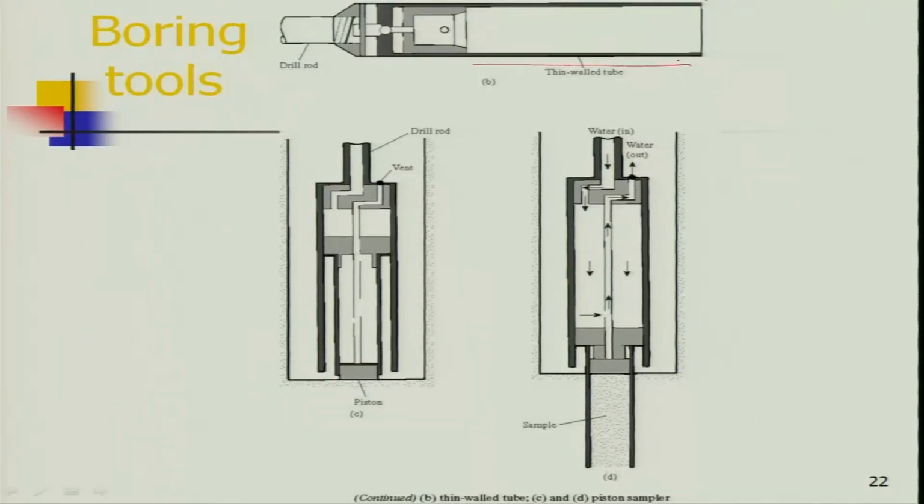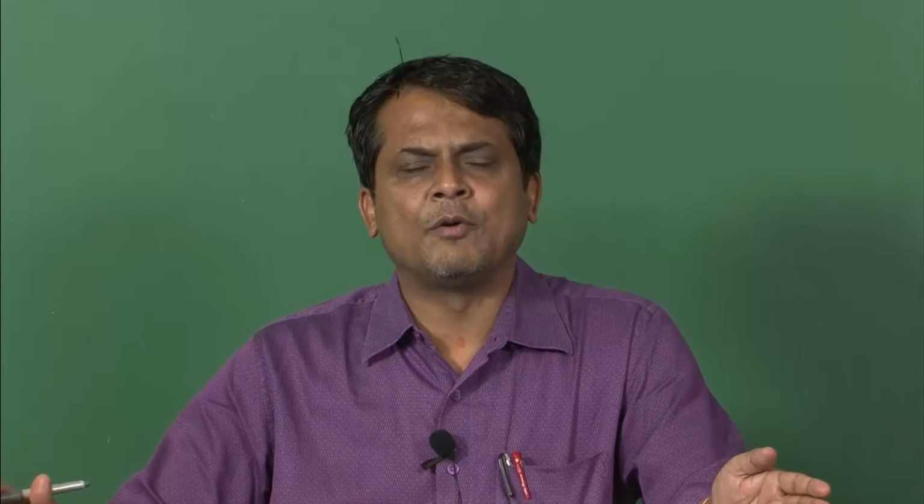These are the boring tools, and I will take one more class afterwards on how to prepare your bore log data, bore log charts, and what information you want to give. This is all a brief description, not in detail, about your soil investigations. Once you complete your soil investigation, you prepare a report. That report has to go to your design section. Based on that report, they will take a call on what kind of foundation they are going to construct. Thank you.